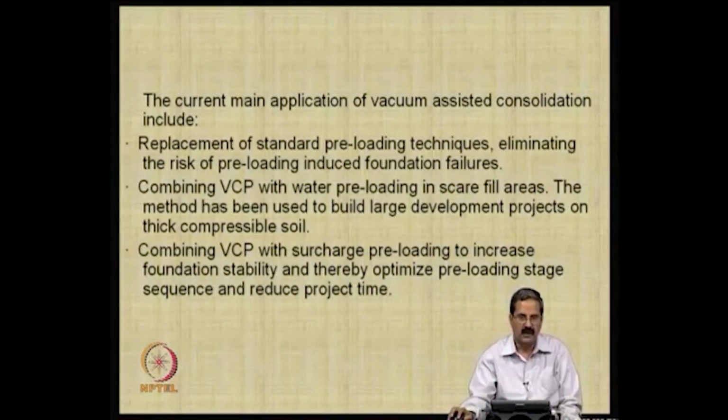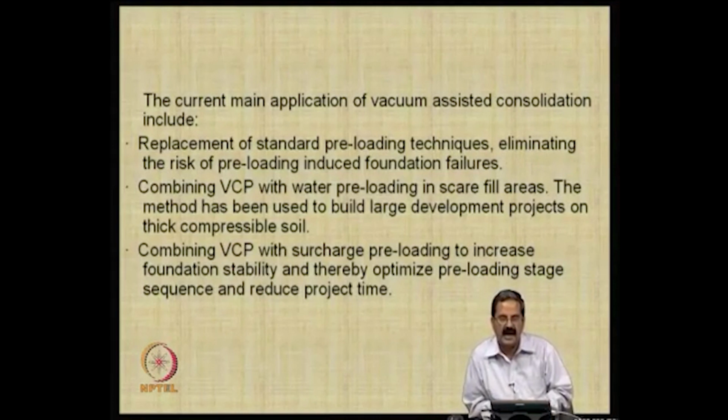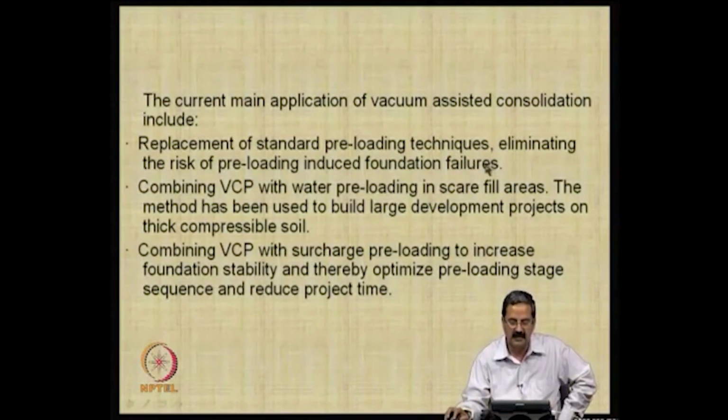What we are trying to see here is that the current main applications of vacuum assisted consolidation include replacement of standard preloading techniques, which means adding a lot of sandbags and so on. The problem is that it eliminates the risk of preloading induced foundation failures. Like, you try to stack all the preload in one place, but it could lead to failure.